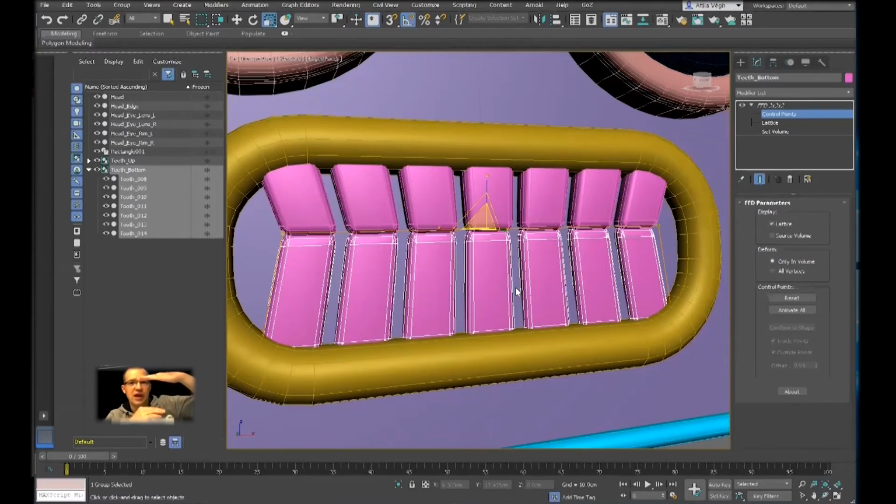But we are lazy again. So instead of creating the lower part arced and the top part arced, we can attach them into a single group. That way we can work on them simultaneously all together, so we don't have to separate up and down. For that, if I want to group an item, I have to select the item first. The bottom one is selected already. So holding down Control, clicking on the top part, but I can't do it. Why? If you look at my screen, why can't I select the other part? I forgot to exit editing mode.